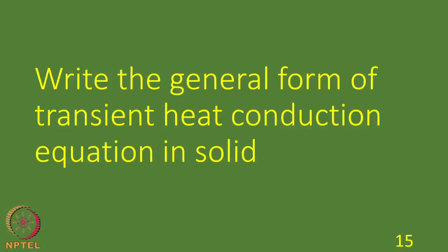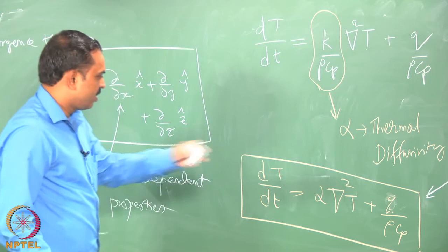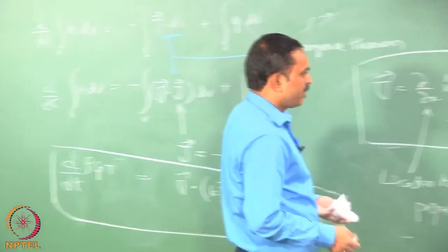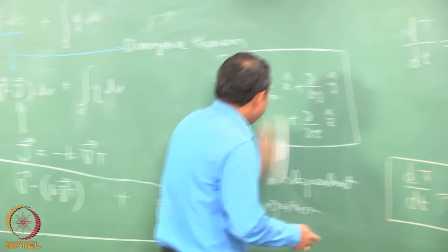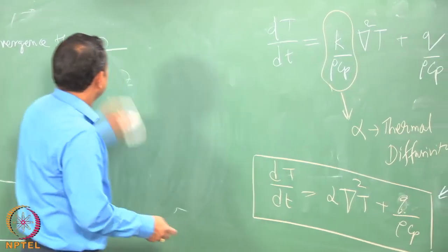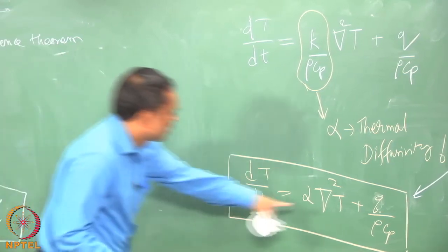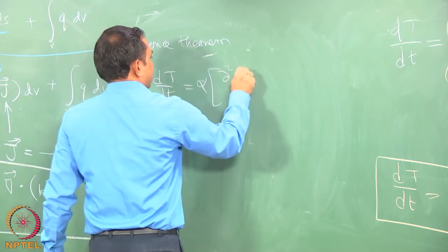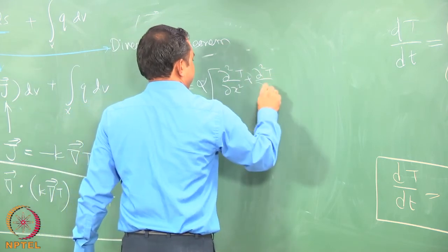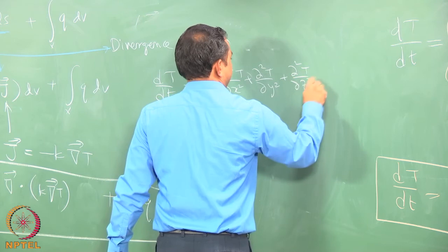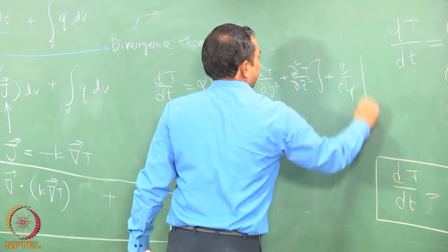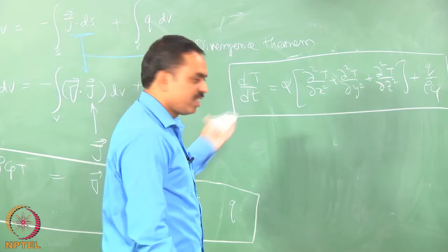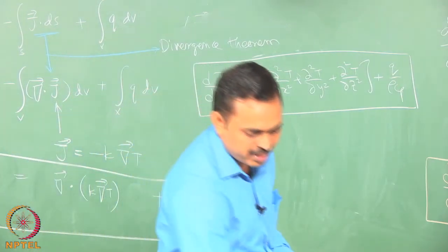The most general form is here. We could also have expressions that look a little bit expanded, and I can write it for you so that you can recognize the expression when you see it in any paper later on. That is nothing but expanding the divergence and the gradient term. You could then write it in this manner. This is a general form that we are looking at, and solving this equation within the domain is basically solving the heat conduction within the domain for welding.